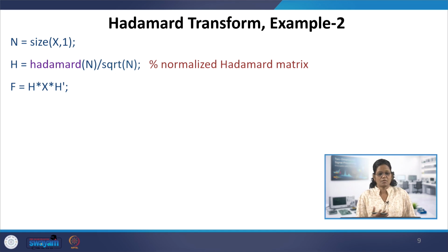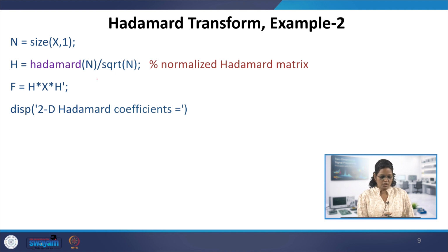In the DFT, it comes from the twiddle factor matrix. So that is for 4 or 2 or 3, depending on n, it is fixed. Similarly in DCT as well as DST. In these transforms, this matrix, the twiddle factor matrix especially, is called the kernel: the Hadamard kernel, the DST kernel, DCT kernel or DFT kernel. From those kernels, using the x here, we can obtain the transformed coefficients.